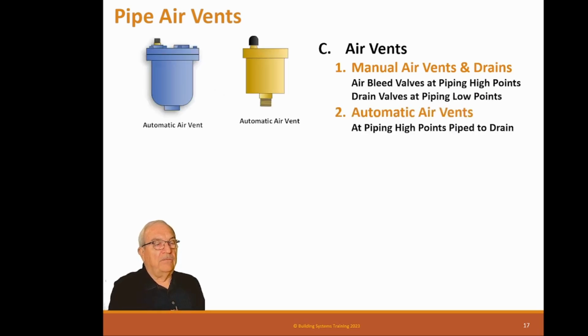We have automatic air vents, and these vents are designed to be at high points of the system, and they have a float valve in there. And anytime air enters it, the float bobbles and lets it escape.